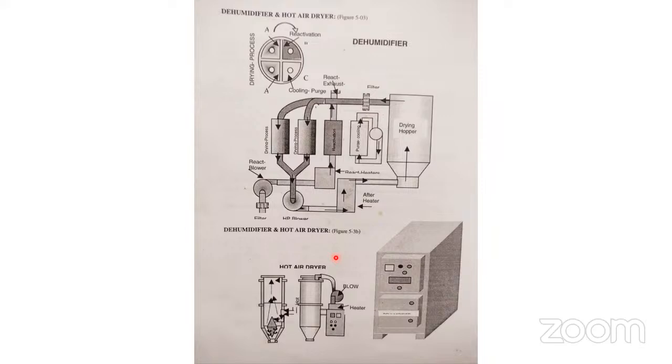They are hydrophobic in nature. Hydrophobic. They are not loving with the water. Hydrophilic means loving with the water. Hydro means water, philic means loving. Hydrophilic, water loving. Which are the water loving polymers? Nylon, ABS, polycarbonate. Which are the hydrophobic polymers? Polypropylene, LDPE. These are hydrophobic. They will never absorb the water inside.